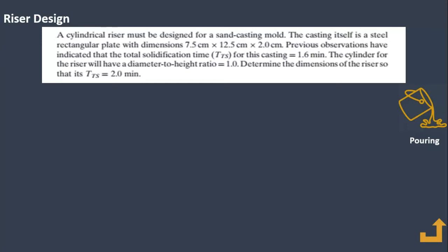So we have two times for solidification. The first one is for the casting and the second one is for the riser. As you can see here, the time for solidification of the casting is less than the time for solidification of the riser.